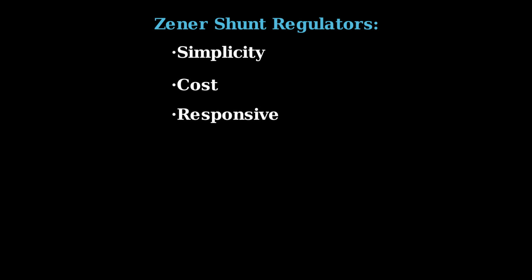The diode is responsive to changes in source voltage. In fact, this leads to a common use of Zeners as shunt regulators: overvoltage protection. If the time the diode spends in the breakdown region is short, the inefficiency is less of a concern. Finally, the inefficiency may be tolerable if the application is low power to begin with.